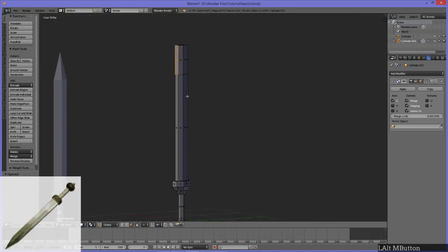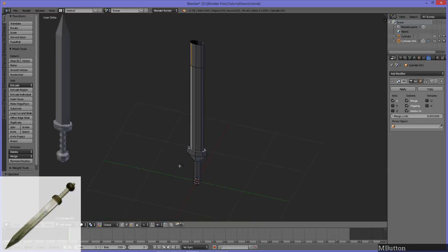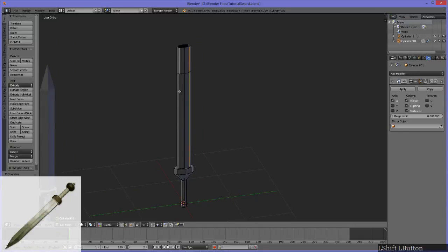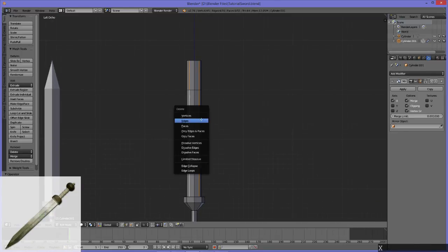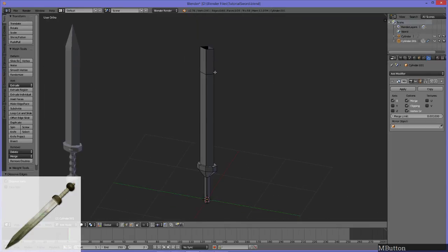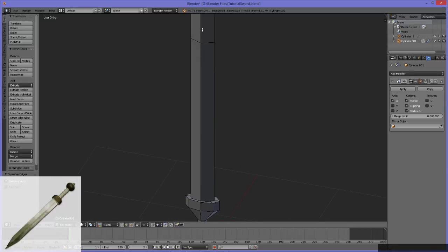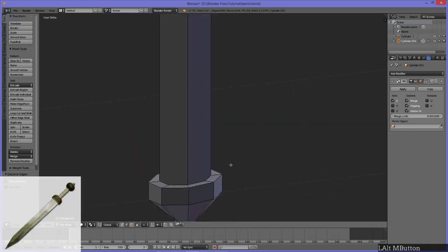Okay. So now for less work, we only have to do these 2 sides instead of all 4. And there will be times when we have to go back to the other way. But I'm going to dissolve these faces, these edges. I'm not going to delete these edges, I'm going to dissolve them. And what that does is it keeps the other geometry there. And you can see that's exactly what we wanted to happen.